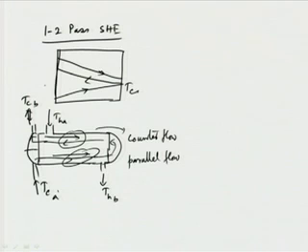So, this is becoming TCI, and here it is TCA, this is TCB for the cold fluid, and this is THA, and this is THB. What we can see here is that TCA to TCI and THA to THB are in parallel, and the other part is in counter flow. The hotter part of the hot fluid meets the hotter part of the cold fluid in counter flow, and the other side is in parallel flow operation.